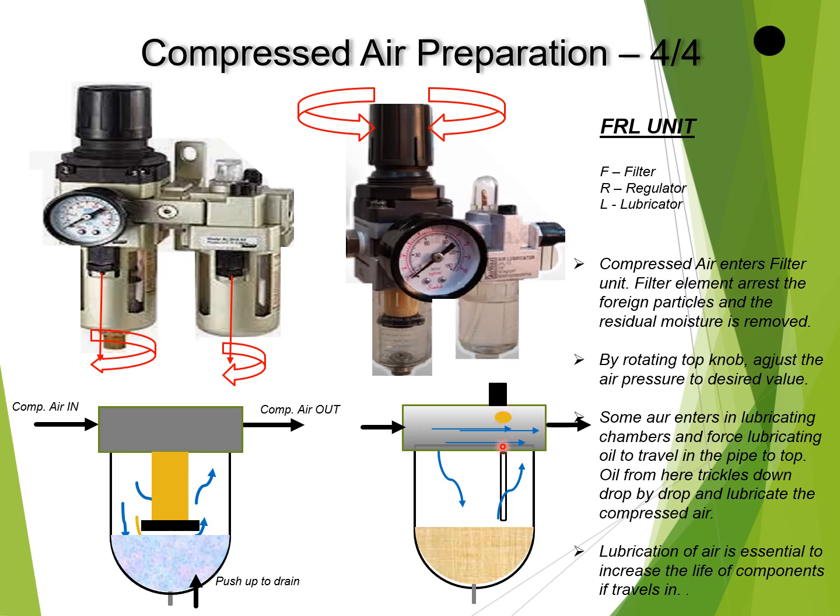This lubrication is very important because in a hydraulic system we are using hydraulic oil as the working medium, but here the work is done by compressed air. So we need to lubricate it so that our pneumatic system is lubricated properly and the life of the pneumatic system is more.